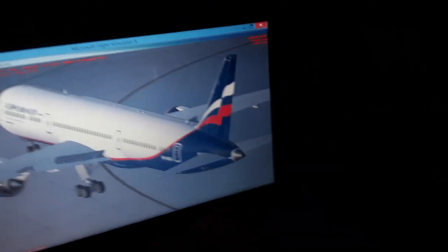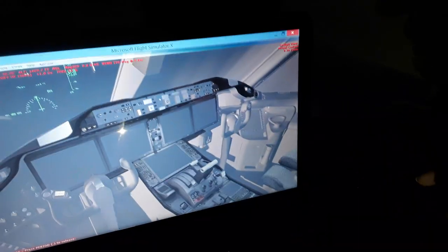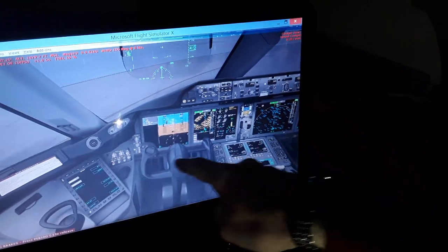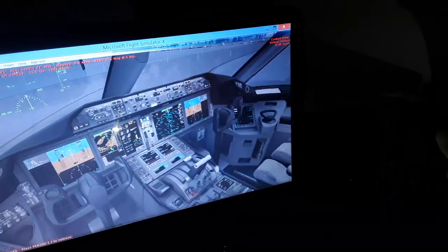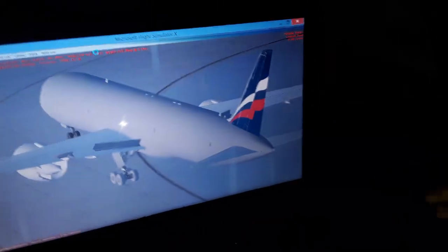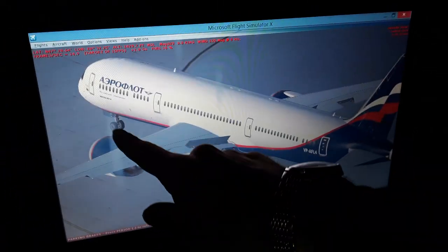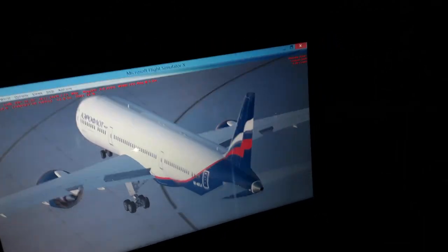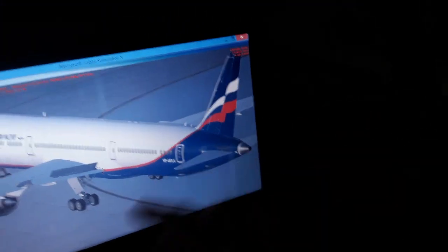And also when we are on the ground and we move the rudder pedals like this, we have also the nose wheel steering through the tiller interconnected in both rudder pedals. So we can use the nose wheel steering also. Over here you can see the forward nose wheel. So we can control left and right turns. I will talk to you about that in a couple of minutes. So we have the elevator, climb and descend like this. As you can see, ailerons and spoilers.